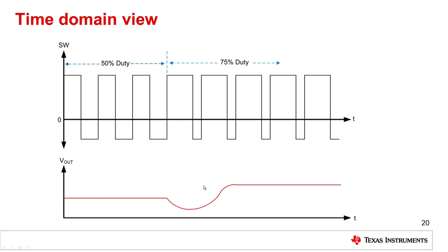This actually has the effect of causing sort of a reversal in the feedback loop phase of your regulator. In other words, the controller increases the duty cycle expecting the output voltage to go up and close the loop using negative feedback. In this case, momentarily, that negative feedback actually changes to positive feedback during this transient, and therefore it can have an adverse effect on your control loop.